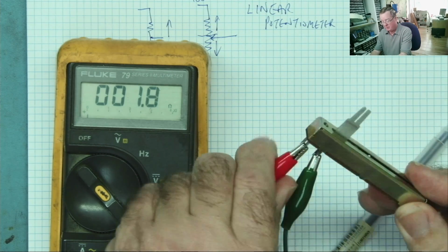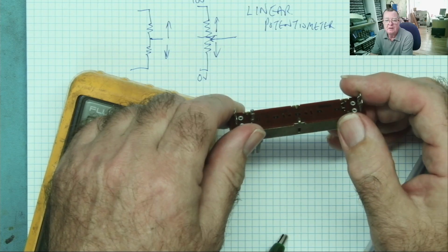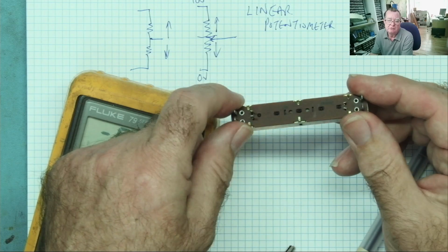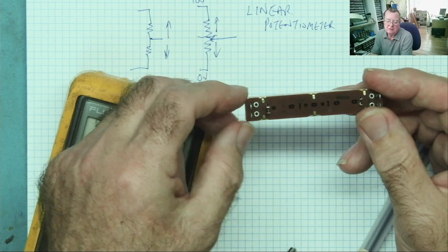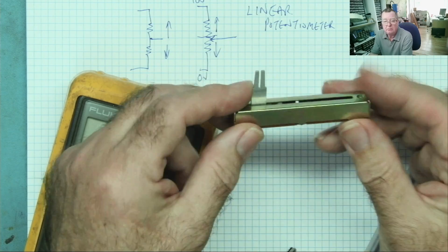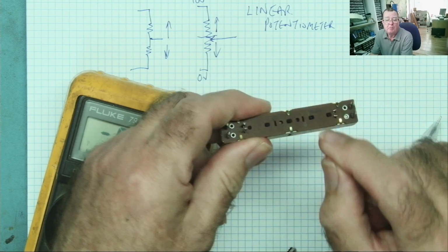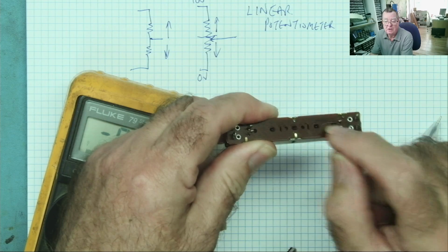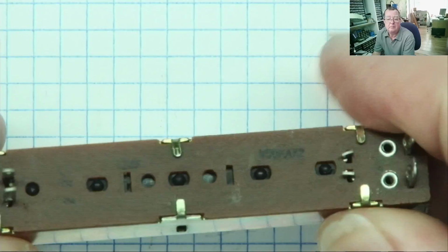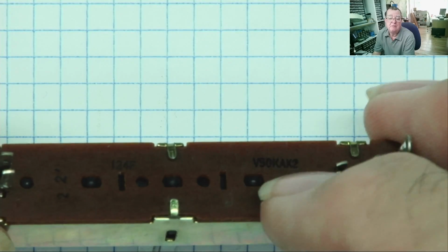The reason we have these, by the way, these are normally for audio circuits. It's one of those strange things with audio and power that to get twice the volume, you need 10 times the actual power or voltage or current. It's probably more correct, yeah, wattage is probably even more correct. So that's why we have these types of potentiometers. So those of you with sharp eyes recognized from the code on there that this is a logarithmic potentiometer. Okay, and those of you who didn't get it right, well, now you know what to look for.